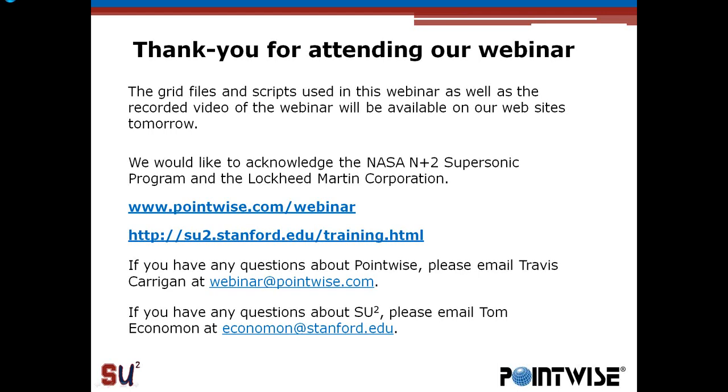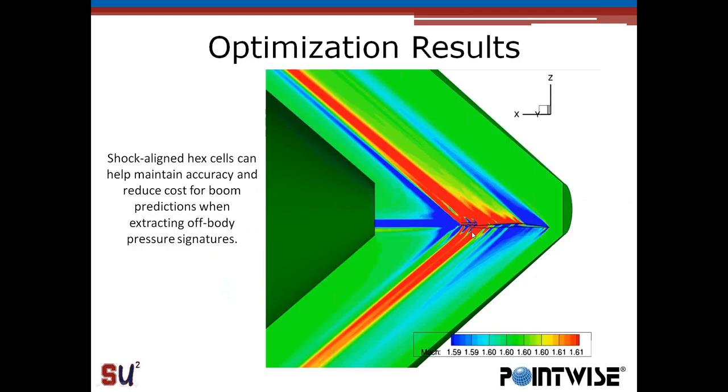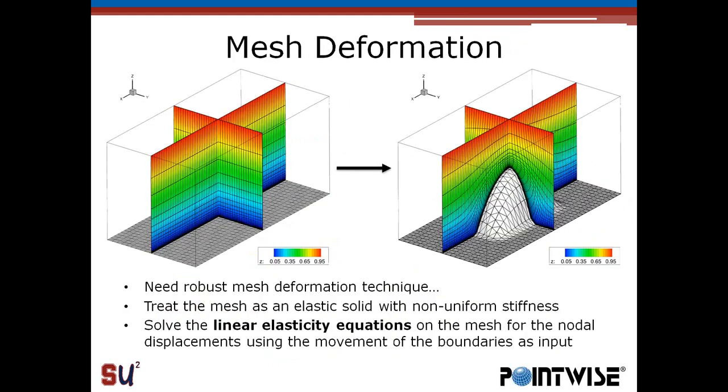Okay. Can the mesh deformation within the optimization handle relatively large changes to the angle of winglets with respect to the wing without creating negative volumes? Yeah, so I would point to the slide I showed early on, where I was demonstrating the volume mesh deformation. This is one of the reasons we picked the linear elasticity approach.